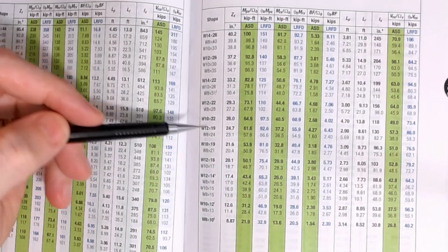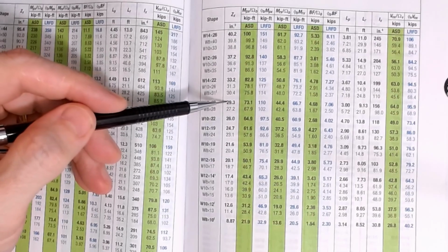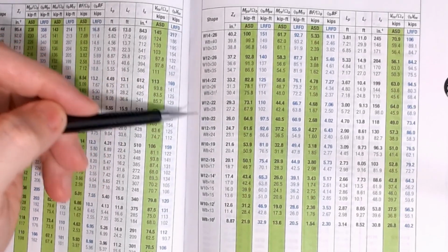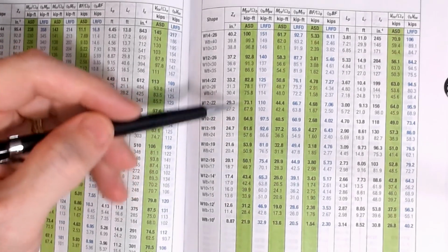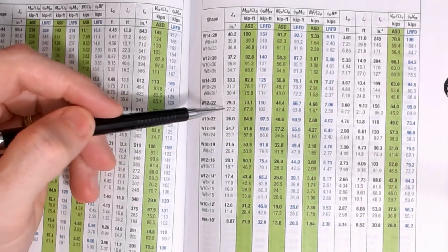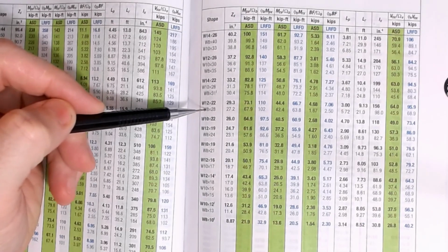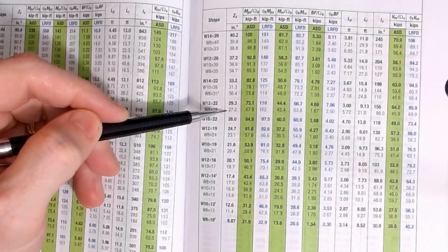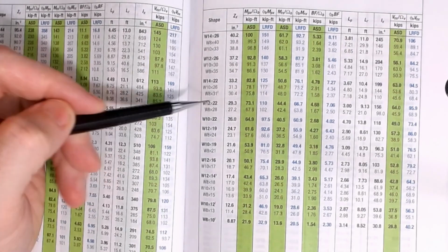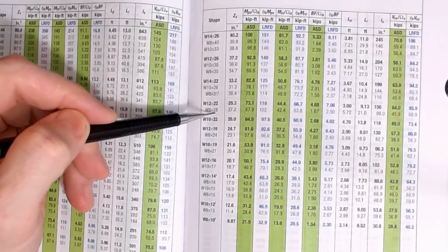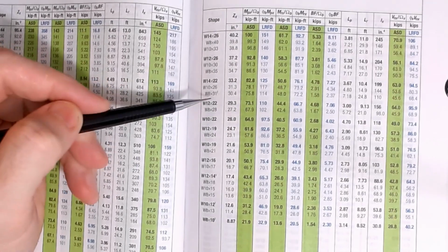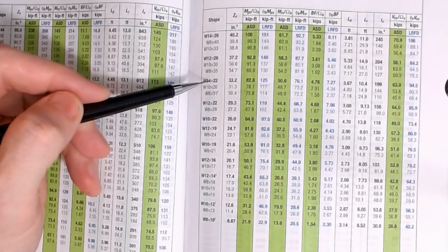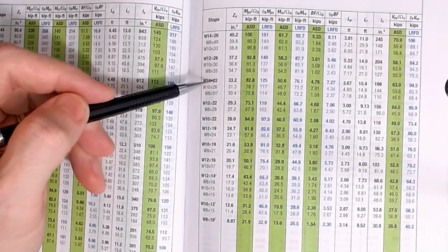So the first one that we come to is 29.3. And you'll notice some of these values are bold and some of them aren't, but they're kind of grouped together. And what happens is some of the section properties, when you have them, that if I say I chose, my number was only 27.1, I might choose this guy. But if you look, the guy that's directly above him in bold is actually lighter than that one. So whenever you're in these groupings, if you're down in one of these that's not the black one on top, you can automatically jump to the lighter one that is the darker one up above.